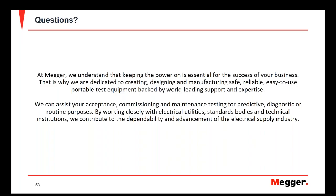You want to make sure that the contacts make a good, solid connection, so that the current is conducted smoothly by the breaker without any heating issues, without any I²R losses. So to check the quality of the contacts, you can do a contact resistance measurement where a DC current is injected through the breaker, with the breaker in the closed condition, and the voltage drop is measured across each pole to find out what the resistance is. And this resistance is a small number, usually in the range of microohms, possibly milliohms in the case of really small breakers, but usually it's in microohms.